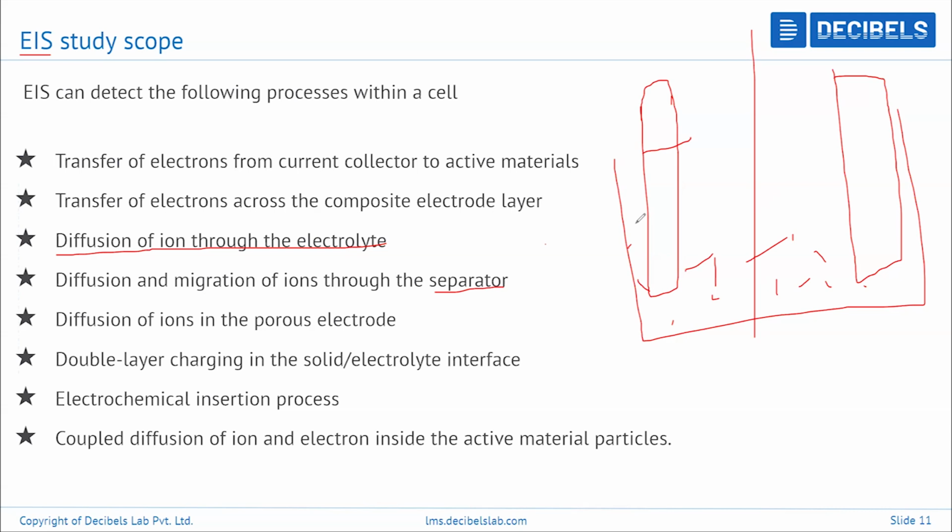Say there is degradation of your electrode; because of that you will be able to see higher resistance. Some irregular particles or plating will be happening over the cell electrodes. We call it lithium plating. It is nothing but an SEI layer, the solid electrolyte interface. Because of that also the resistance is going to increase, because the diffusion of ions to the electrode gets some kind of hindrance, and that shows up as resistance. In the same way there are many more, and these can be captured through EIS.